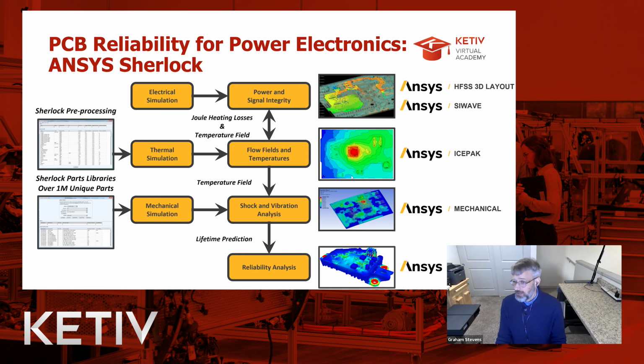But then you can marry it with HFSS, SIwave, Icepak, mechanical simulations with regards to powered signal integrity, temperature, or shock and vibration analysis, dialing the accuracy for that reliability estimate to very high levels, and estimate the reliability of your PCB or your system as a whole.